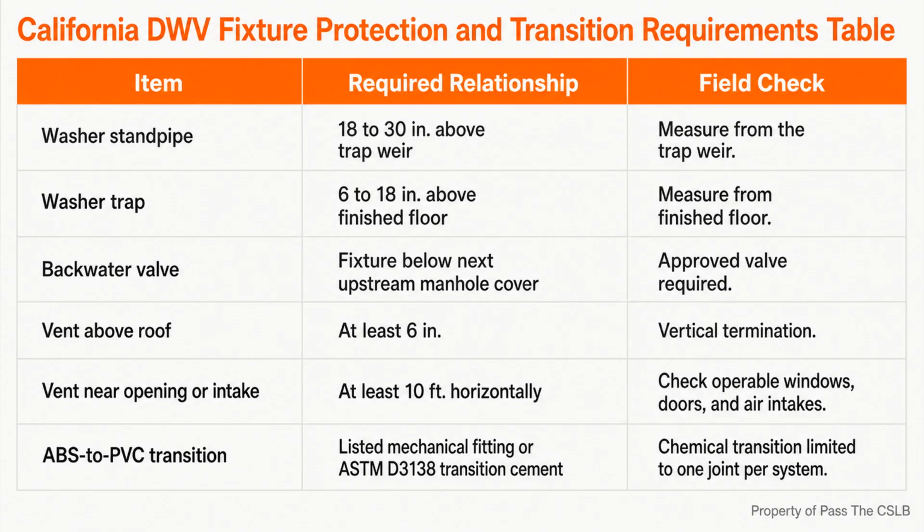Plumbing rough-in often collides with framing, and that conflict belongs squarely in general B coordination. For a stud in a load-bearing partition, the source material allows a notch up to 25% of the stud depth and a bored hole up to 40%. Boring may increase to 60% when the stud is doubled, but no more than 2 successive doubled studs may be bored that way. For a non-bearing partition, a single stud may be notched up to 40% or bored up to 60% of its width. The bearing condition changes the allowed cut, so I would not approve a hole based only on how much wood appears to remain.